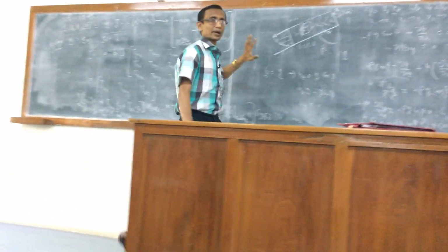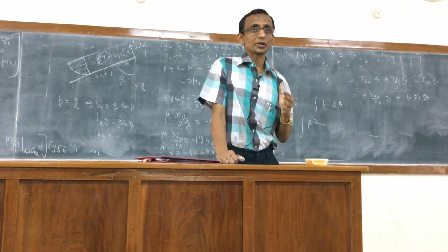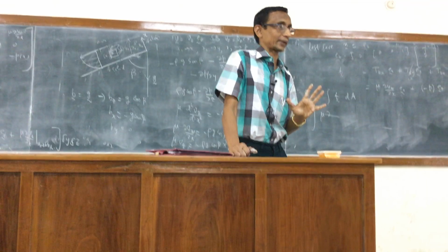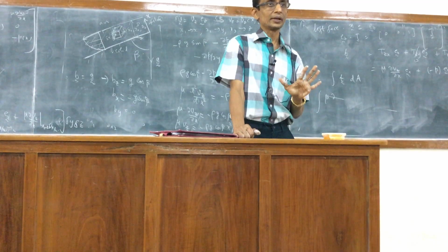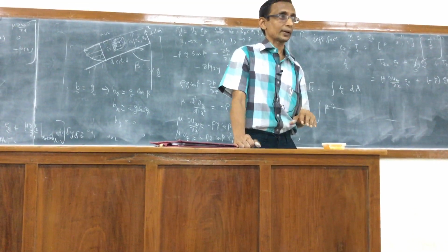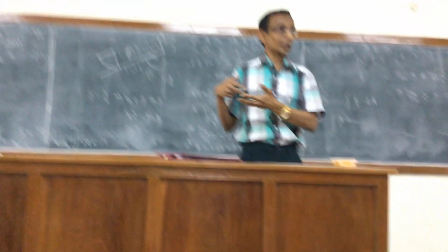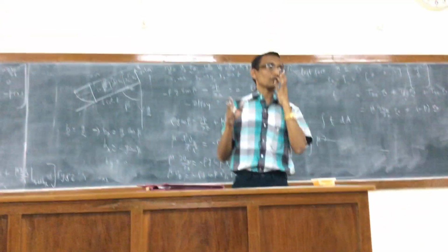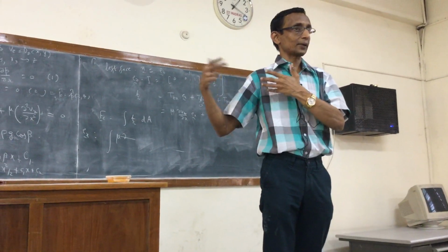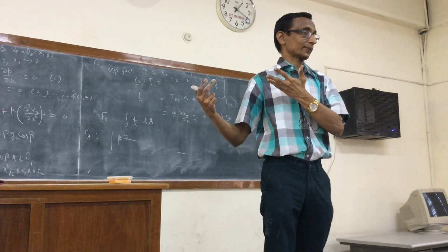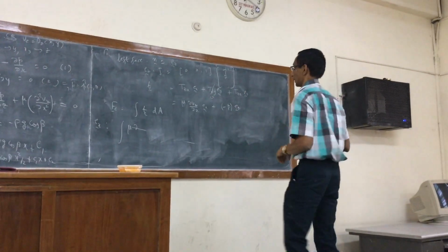We've already established that the two off-diagonal elements that would not vanish are both given by mu times dvz by dx. There's no question of dvx by dz here. You have to go back and think why that is the case. We arrived at this after doing all those manipulations involving D and it being the symmetric part of the velocity gradient. For the general case, you will get half times dvx by dz plus dvz by dx. Here dvx by dz is 0, so you are getting only the dvz by dx.